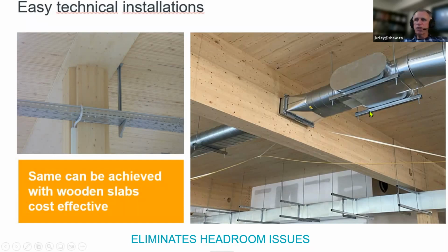So that's an extra engineering cost. And you can see headroom issues, bulkhead issues, cosmetic issues. And you can see here where the hole was put into the beam by the CNC machine of the glulam manufacturer, and now it's not required. So mechanical systems change, building design changes, and you're stuck with that for the life of the building.